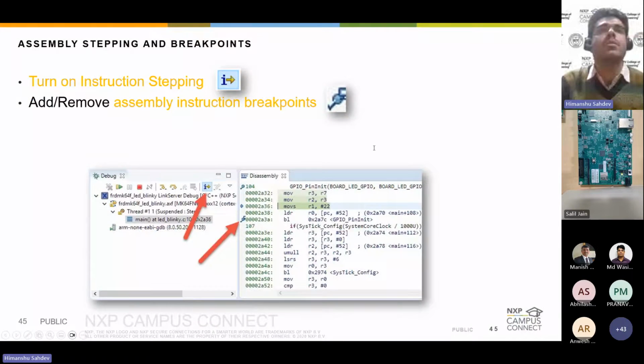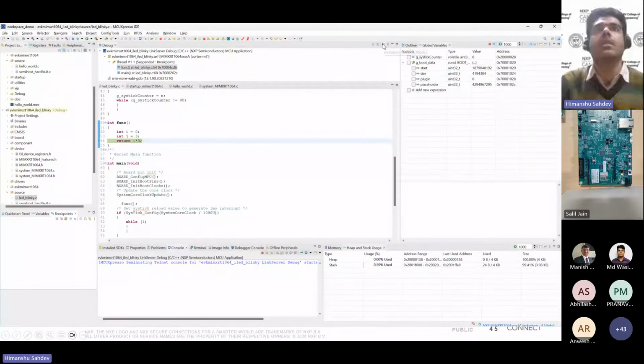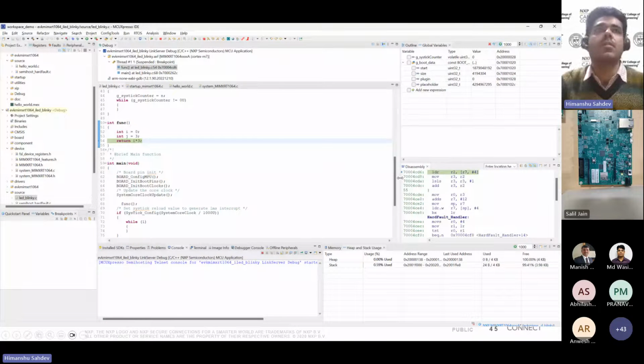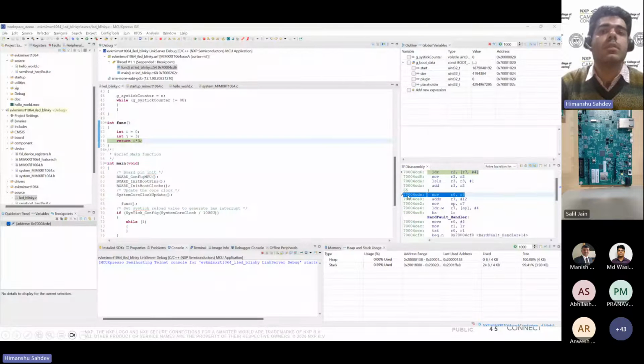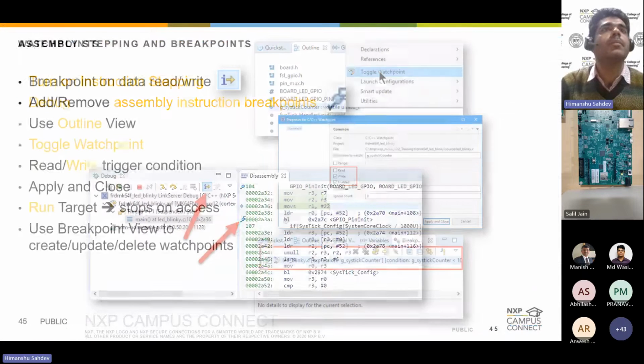Okay, so disassembly we also have here. We can see the disassembly. If you click this instruction button here we can see the disassembly of the same program on the particular line. If we want to debug it here, we can also mark a breakpoint on this line. All you need to do is tap 2 times, and the symbol of the breakpoint appears, and we can also debug in the disassembly.